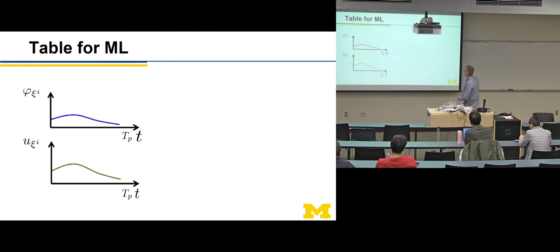And let me show you how. So we have all of these trajectories, and we have all of the corresponding open loop feedback controllers. Why don't we have a closed loop controller? We don't know how to compute one. What do we have? A tool that computes trajectories super fast. So can we take that tool and turn it into a really good feedback controller? So this is what Dennis does.